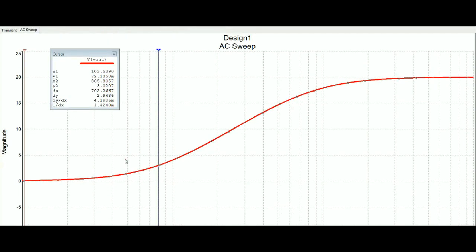It's called a step filter. And if we were to see this, say, in an audio amplifier system, it would be a bass cut circuit, and the cut would be limited to 20 decibels. It couldn't cut any more than that. So that's pretty cool. Let us go back now and take a look at the circuit and see why that is.